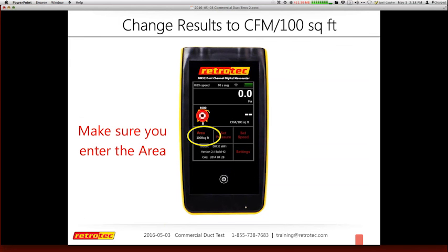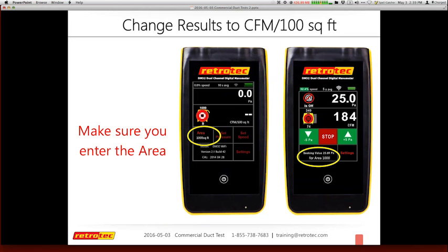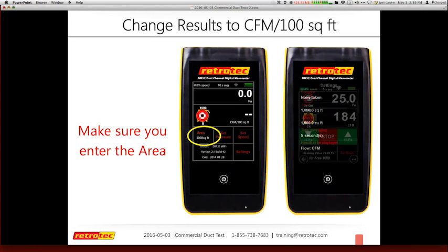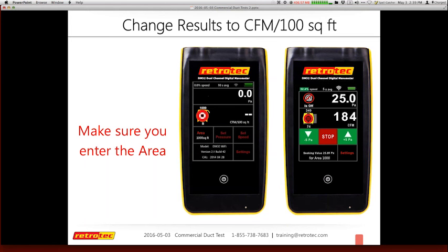So commercial is based upon the surface area of the ducts being tested. You actually are going to calculate all the different sides. Sometimes there may only be one end cap, depending on how you're going to do your test. There may be two end caps, depending on what it's connected to or what you've isolated. But again, you're going to figure out your surface area, and that's usually the leakage that you're looking for, which is your compliance path.